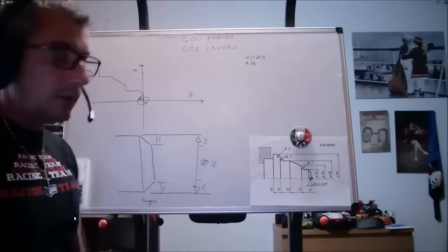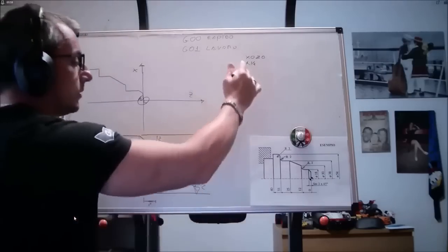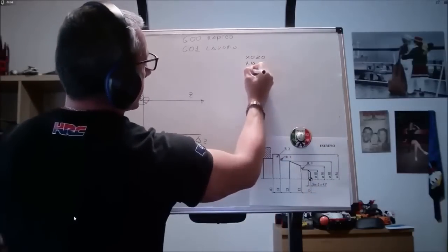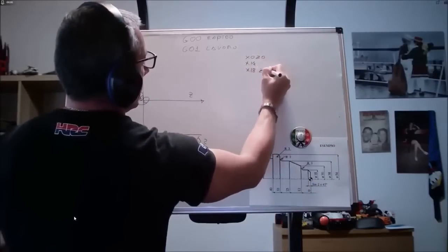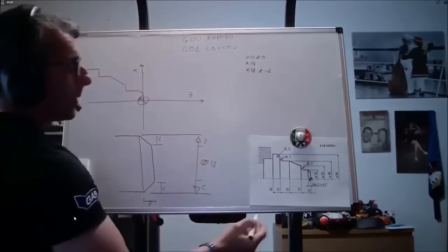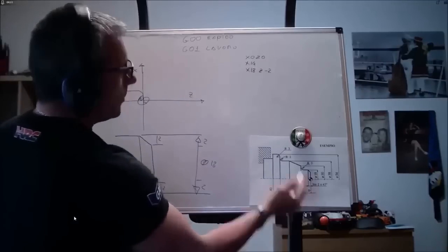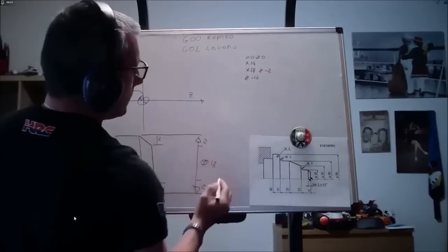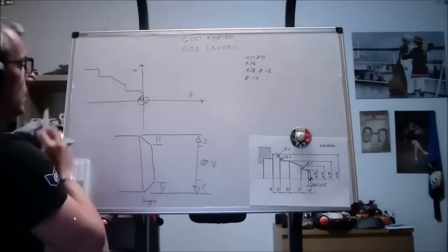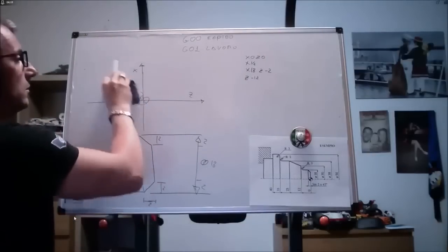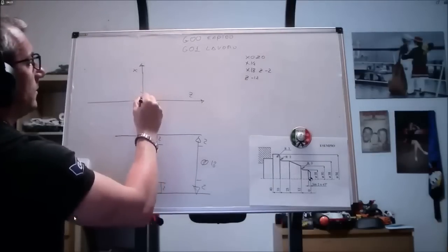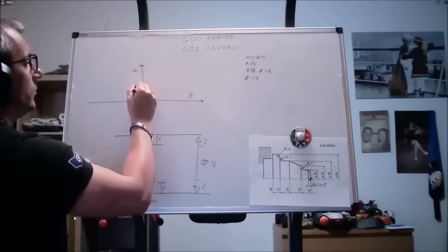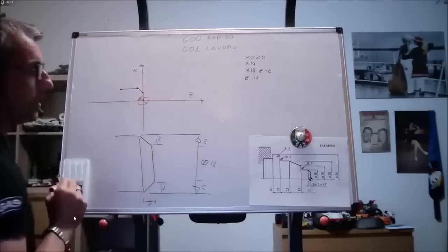Okay, being a diameter, we go to x14, second point of the chamfer, so yes, we go to x18 and z minus 2. Then we move to z minus 12. Do you see our point in space? Erase x0, z0, x14, x18, z minus 2, z minus 12.